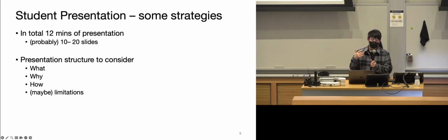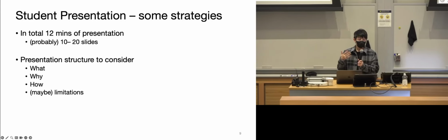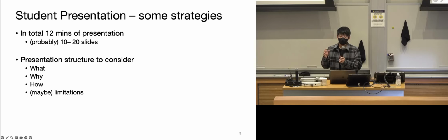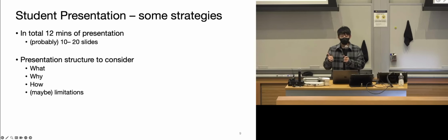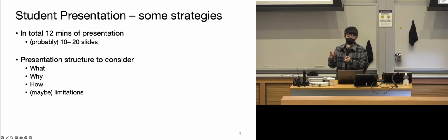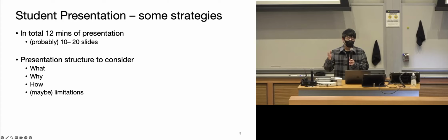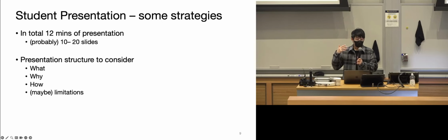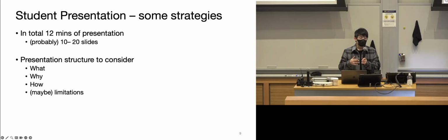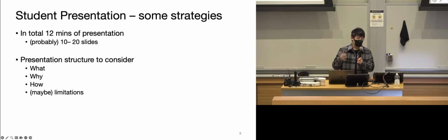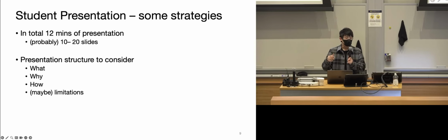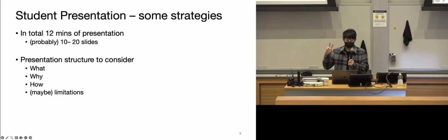And how, basically, is how to use the sensor modules or peripherals or protocols you're presenting. It will be great if you can include both the general strategy, how people normally would use this, as well as your specific sensors. For example, if you present an IMU, you could use various different ways, I2C, SPI. It would be great to have your specific sensors that you chose, the ones maybe you got from Bosch or from SparkFun, etc., and then how you interact with that sensor in your own project. So that's the how.